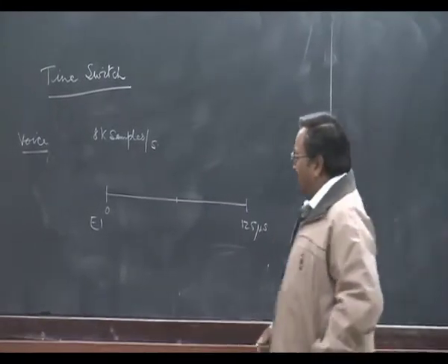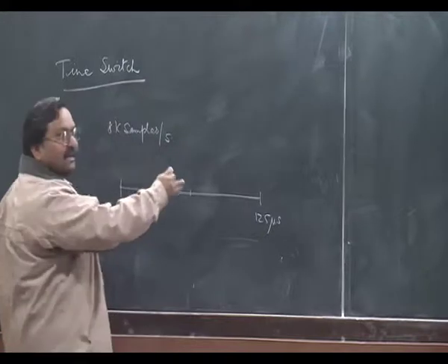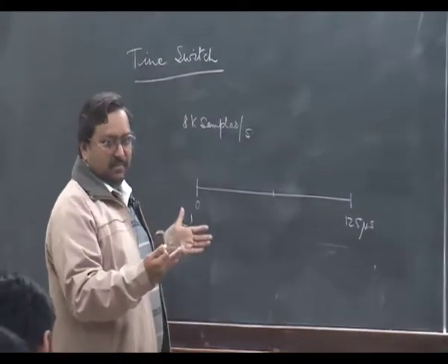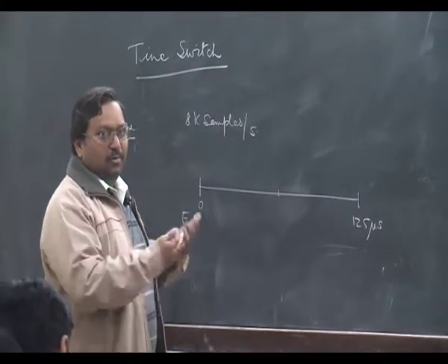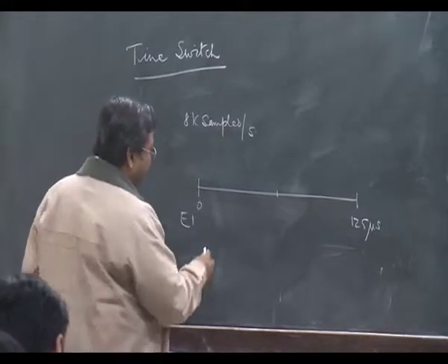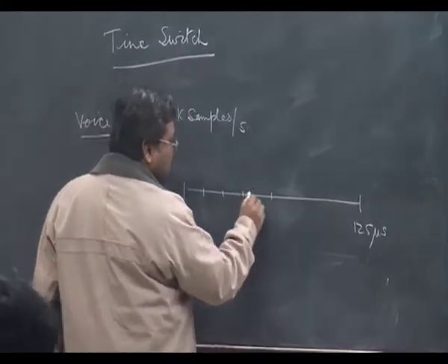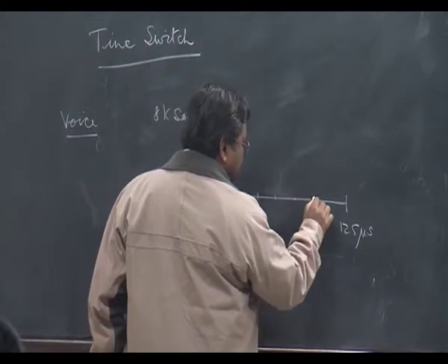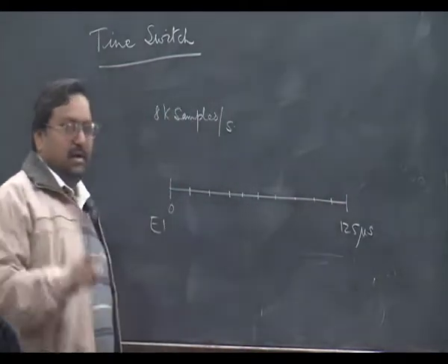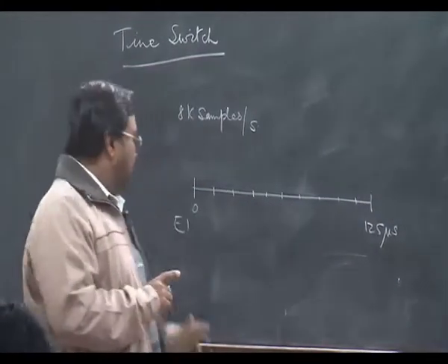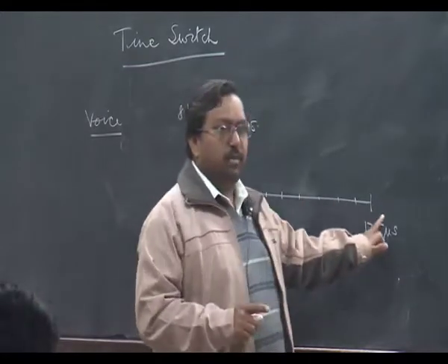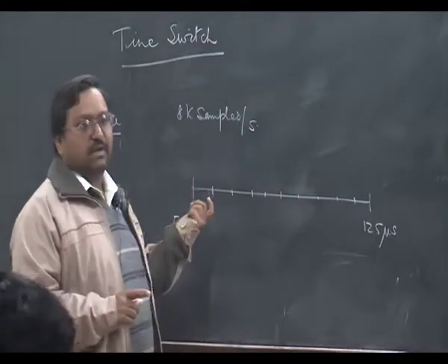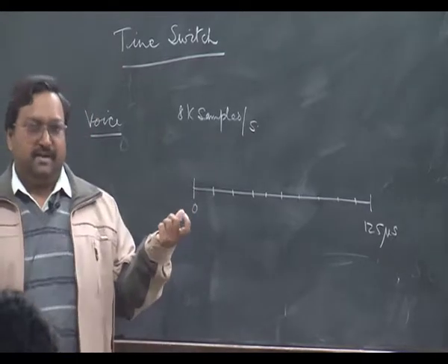So this actually means I am anyway getting a time multiplexed signal which is available. Now how to do switching with that is the question. So usually there will be slots. Another important thing is that these frame boundaries are extremely important, because the slot's location is what identifies the circuit.